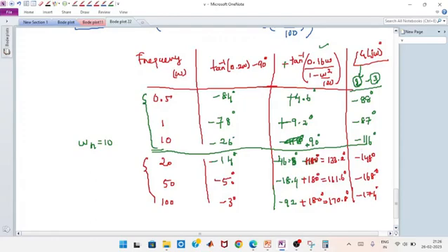For the corner frequency, look here. We have the provision in our calculator to calculate tan inverse only for 0 to 90. But for the second order quadratic factors, the value may vary from 0 to 180. For this one, after the natural frequency or the corner frequency, I am adding 180 degrees at each and every term. That's what I am doing. I hope you can follow this.